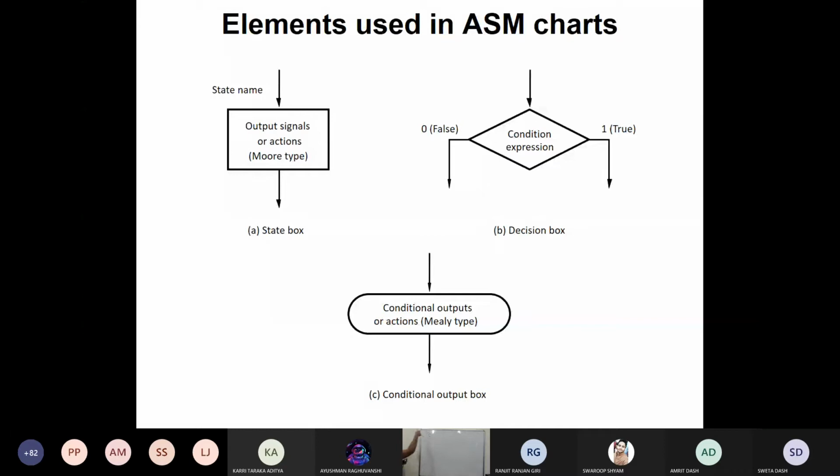Okay, so this is S0, the start state. Just a second. S0 is already provided as 0 by 0, right? And it is going to S1 with 1 by 0. The purpose of this particular graph is 101 detection, it seems. So already we have done that. Consider that we have already done it. So we have already done some of this.